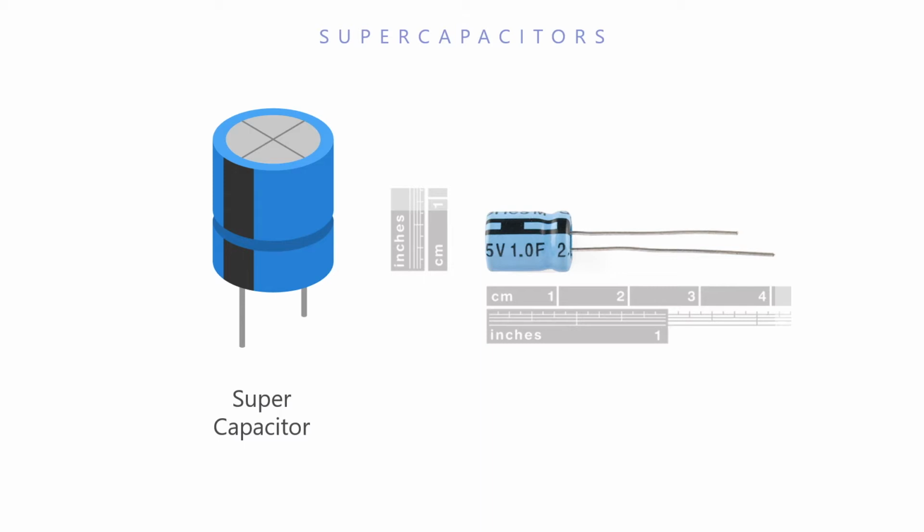While they can store a huge amount of charge, these capacitors can't deal with very high voltages. This 1 farad capacitor is only rated for 5 volts max. Any more voltage will destroy this capacitor. Supercapacitors are also commonly placed in series to achieve a high voltage rating while reducing total capacitance. The main application for supercapacitors is in storing and releasing energy, just like batteries, which are their main competition. While supercapacitors can't hold as much energy as an equally sized battery, they can release it much faster and they usually have a much longer lifespan.